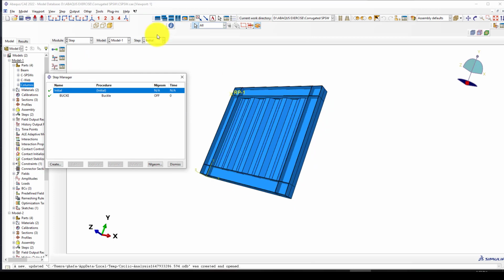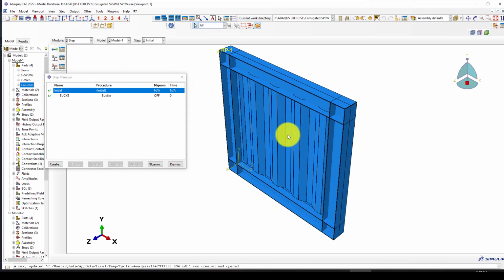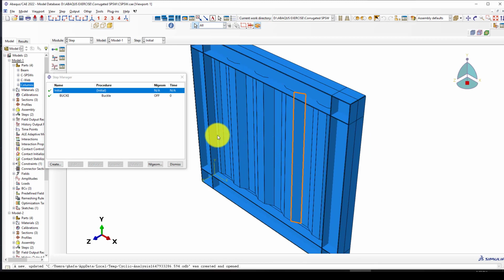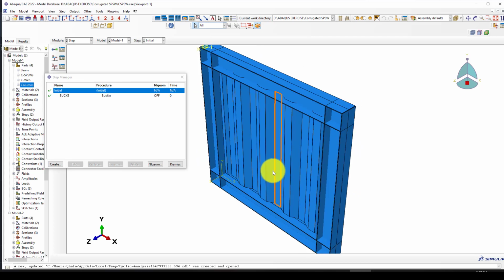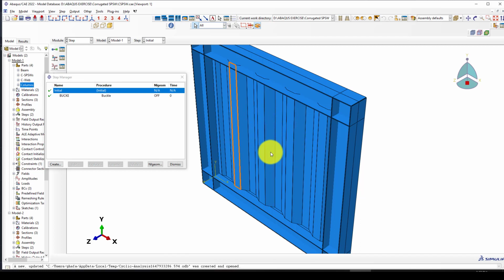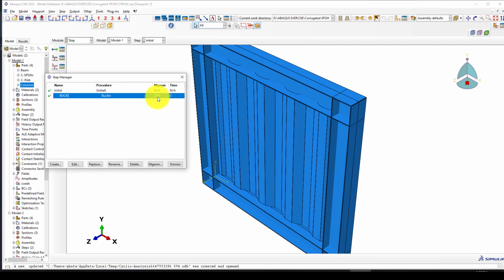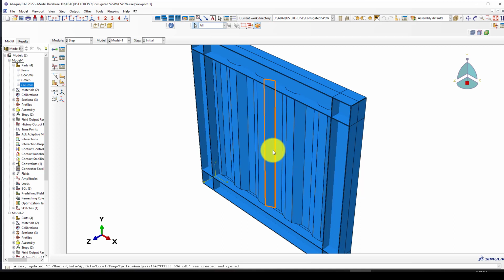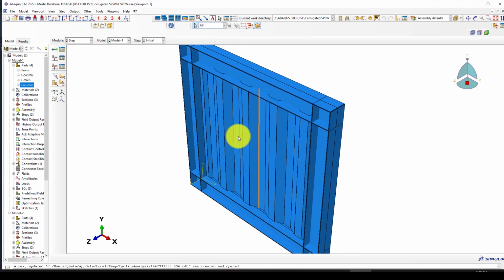In the first step, we should utilize the post-buckling behavior of the steel plate shear wall. So we need to consider, in the second analysis, whether dynamic or static, the amplification of the web plate. Therefore we need a buckling analysis to see the buckling of the web, and then we will use some mode scaling in the next analysis.